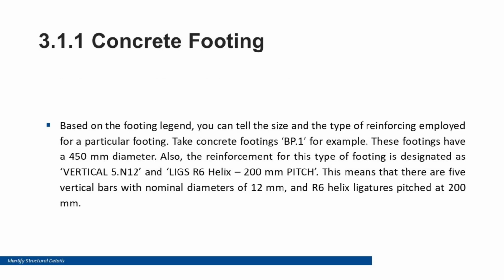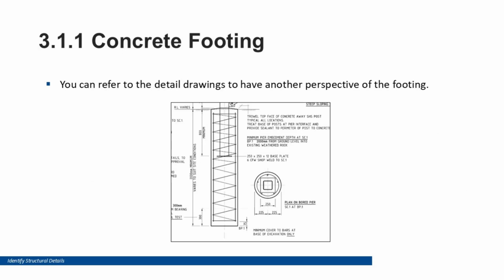The schedule will tell you the diameter, such as 450 millimeters, the reinforcement required, such as 5N12 vertical bars, and the spacing of ligatures, such as R6 helix at 200 millimeters pitch. This information must match the structural specifications document. Accurate understanding helps avoid foundation failures or non-compliance with engineering requirements.